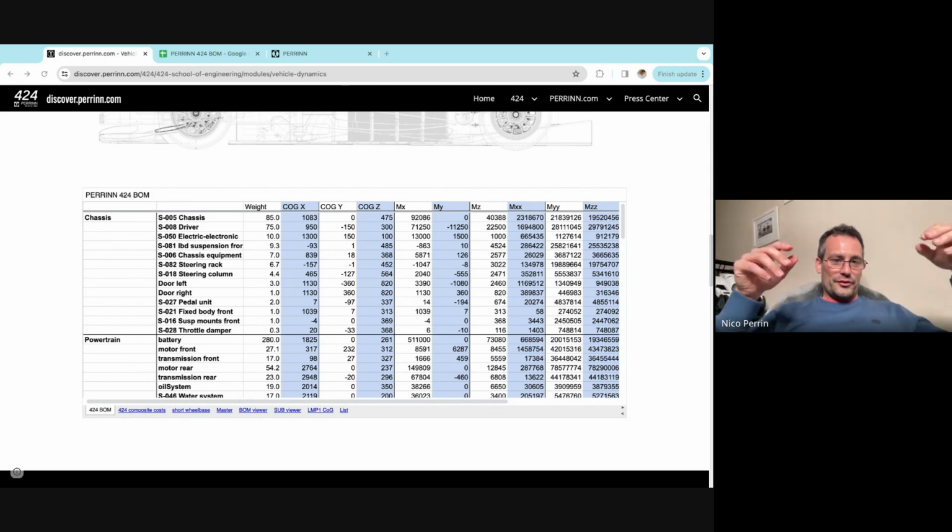Why? Because you're not saturating the front as much, and you can use a bit more of the rear potential of the tire. Remember, the slip angle was high at the front, not so high at the rear. There is a bit of margin left at the rear that we are not using. So we need to increase the oversteer. Some drivers are struggling to drive like this. So yes, there are some differences. So that is the answer.